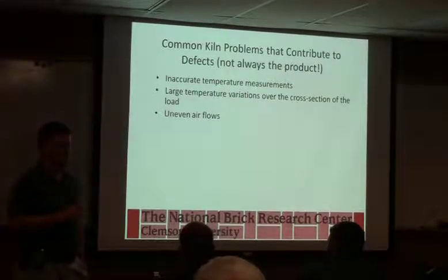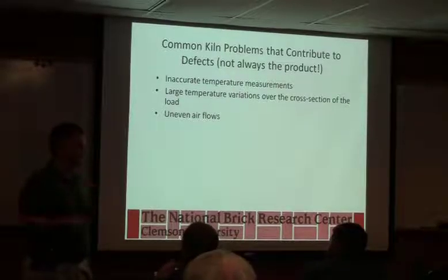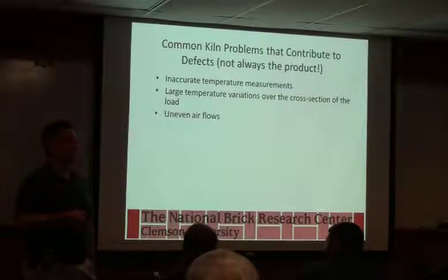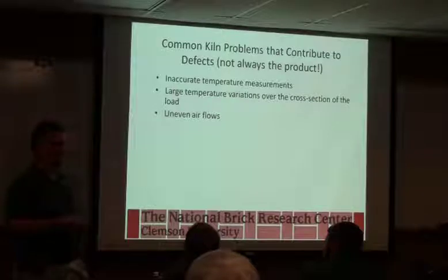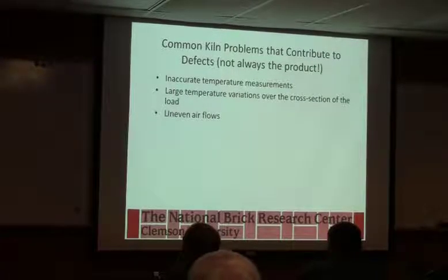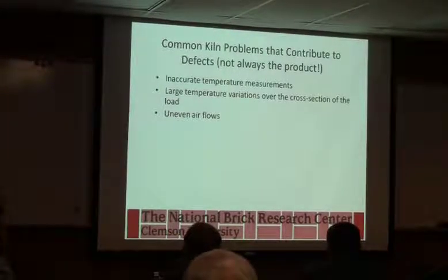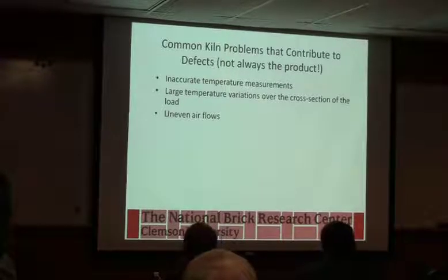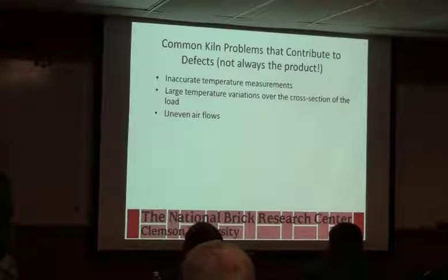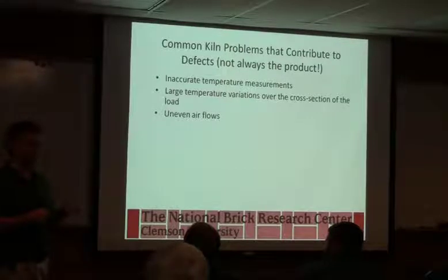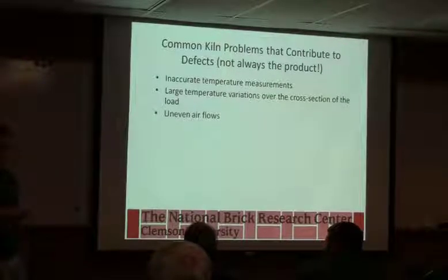If you actually break a brick apart and it's got a black core to it, what's the black? Iron. You would think, but typically not. What's happening is the black is actually the organic, the carbon there, but it has a higher affinity for the oxygen, so it actually strips oxygen off of your iron and turns your iron from red to black. So it takes it from Fe2O3 to Fe3O4, which sounds kind of odd in that it's going from O3 to O4, that's another oxygen, but it's per how many irons you have there. So Fe2O3 actually is more oxygenated than Fe3O4. Okay.